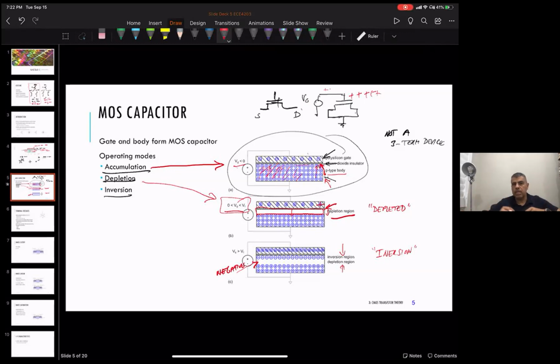So you get an electron and hole pair, the electron goes in one direction, the hole goes in another, and sooner or later an electron will see another hole and they recombine. So you have this process in a piece of silicon called generation recombination. And it happens more and more as you get to higher temperatures. I mean, temperatures above minus 273, whatever, Celsius. So essentially at any temperature, you have this generation recombination.